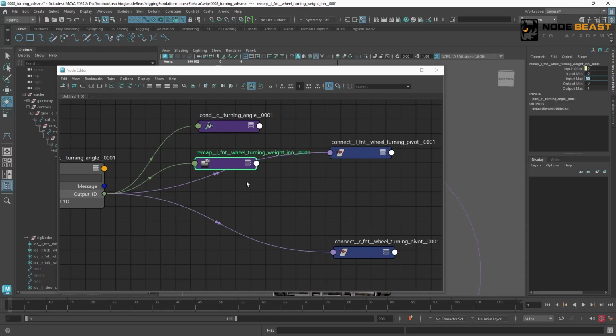If we need a very precise value, we might need to look up the car model's documentation to see its corresponding maximum angle and set it. Okay, we know 30 degrees is the angle for turning left. This is the left wheel, so the multiplication factor will be larger. Let's set it to 1.2. And the minimum value will be consistent with the car body's rotation.